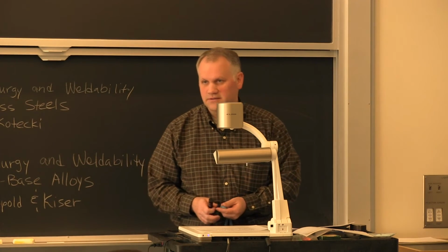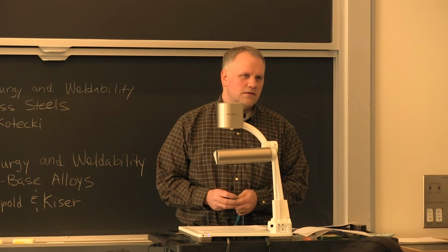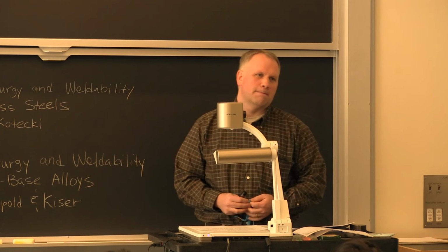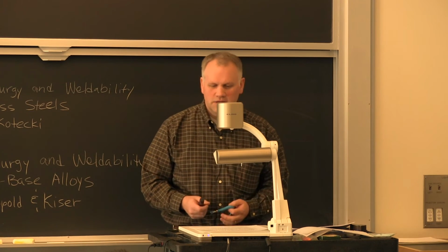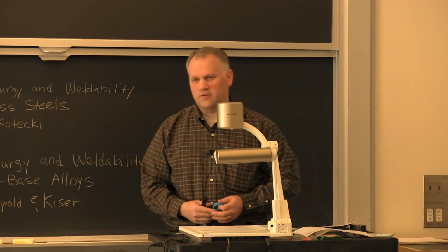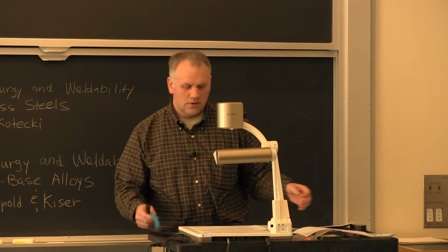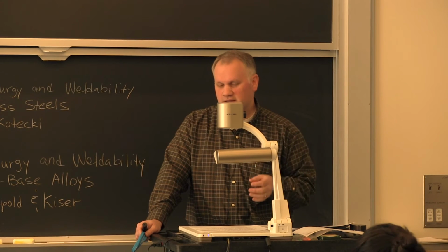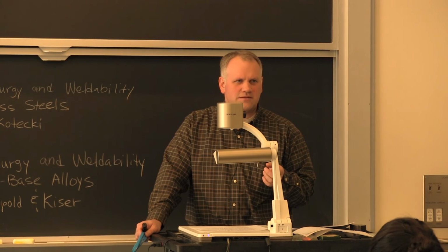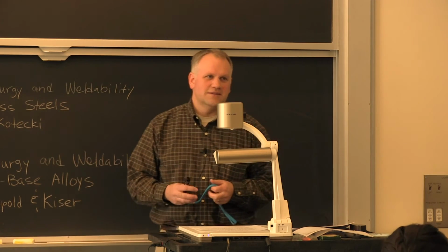Stress corrosion cracking. Have you talked about that, or will you talk about that? No, I do it during the corrosion module at some point, but I haven't really talked a lot about stress corrosion. Certainly not in this version. Okay. Stress corrosion cracking is a form of cracking that can happen mainly in stainless steels, where you've got an environment that is corrosive. You've got a stress, and what's the third thing? A susceptible microstructure. And we did sort of talk about it yesterday.